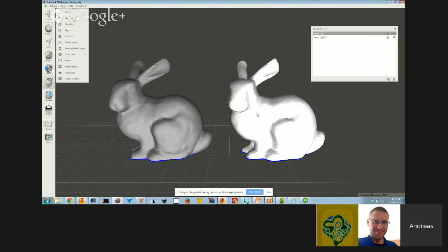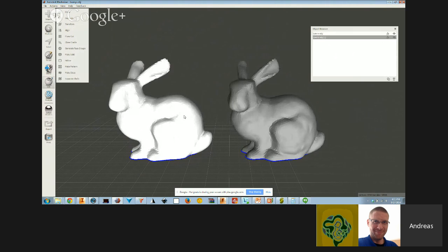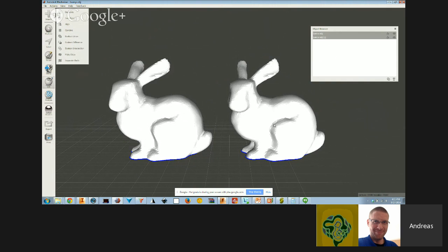So here you saw the very basics of, okay, I have one object selected, it's going to operate on that one object. Now, if I multi-select and I use Shift to multi-select these objects, you'll see I have a whole different set of options here. Now I have Booleans available, for example, and I can go in and do a Boolean. And just to show that, why don't I go ahead and do a Boolean?